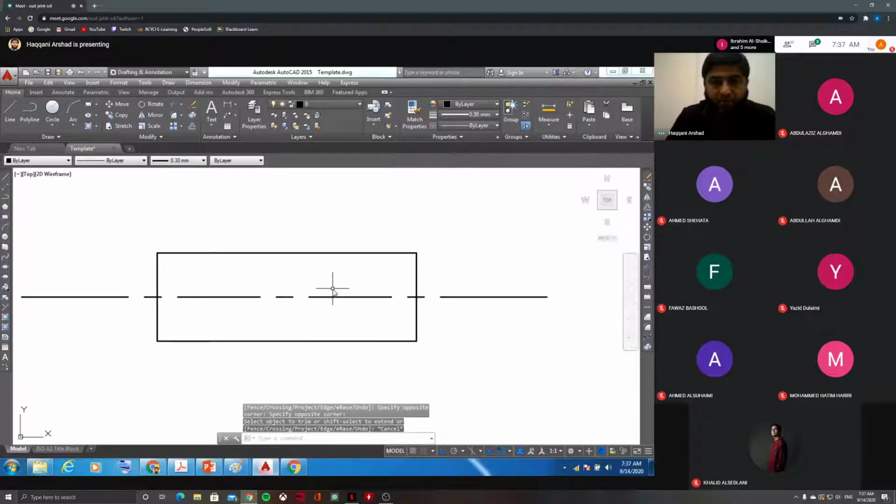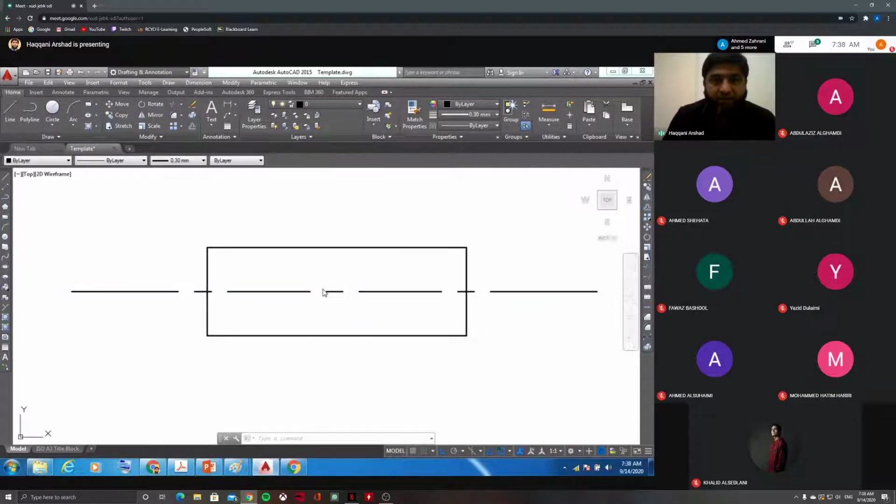Always remember, center line is a must. Any line type, whether it is a hidden line or a center line, you must consider that. And whenever there is a cylindrical body, any screw thread is a cylindrical, circular body, so you must represent it with the center lines. Now the thread length is given. I'll show you the dimension as well.